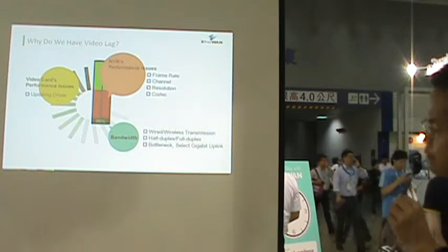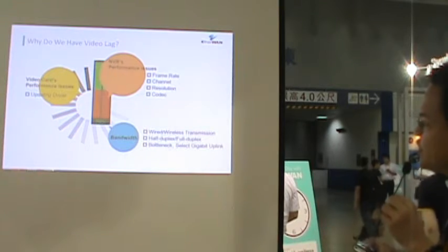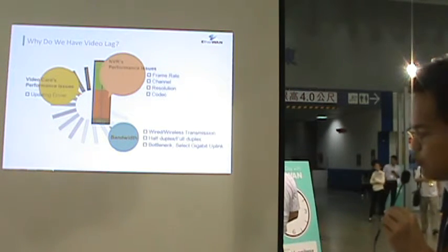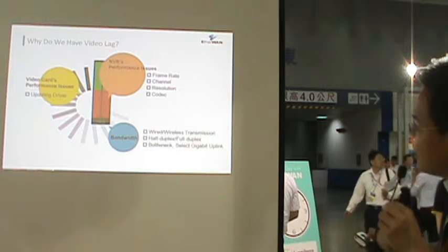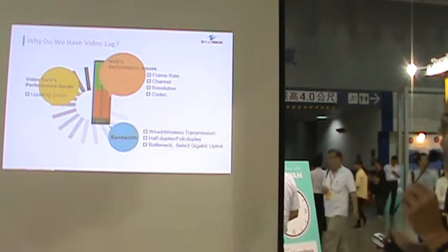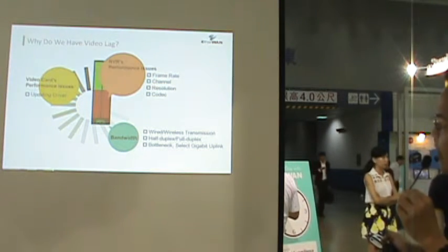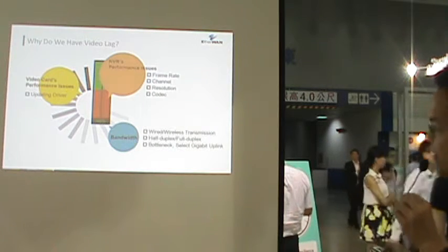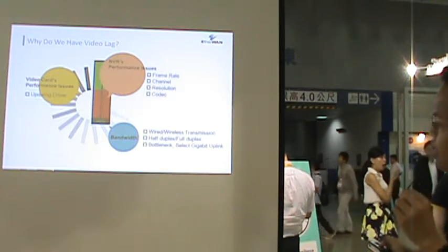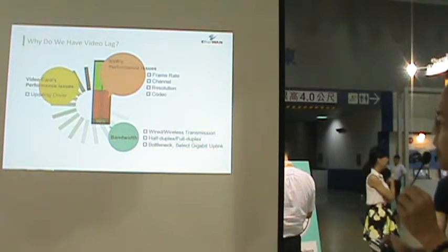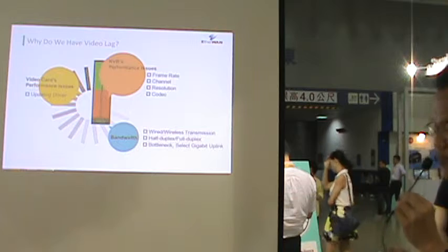Okay, channels. We have to make sure how many channels we purchased for the NVR. For instance, let's say the NVR supports 3 cameras. So you cannot add a 4th camera to it, because of the channel limit. And each channel will have a specified resolution as well. Let's say the maximum resolution that a channel can support is Full HD, and you configure more, let's say 3 megapixel, it won't work that way. Also for the resolution, sometimes we can reduce the resolution to solve the latency issue.